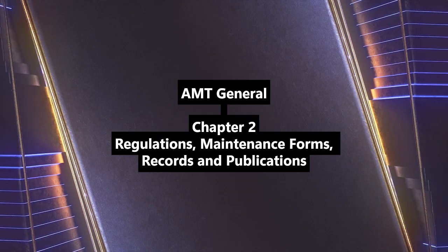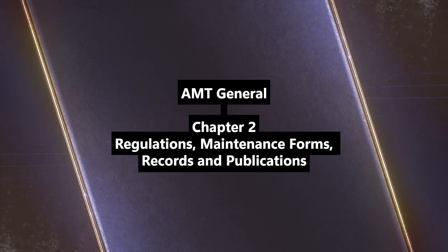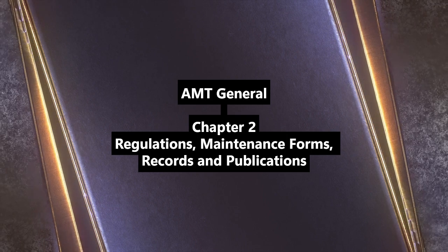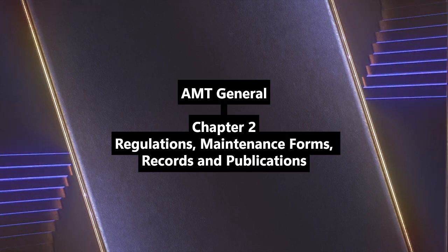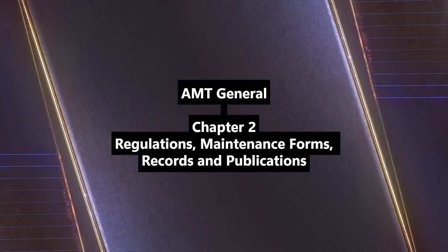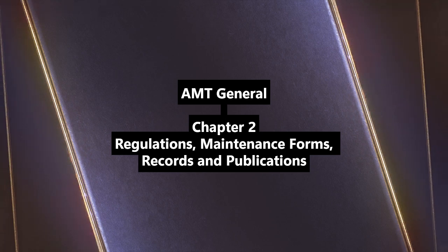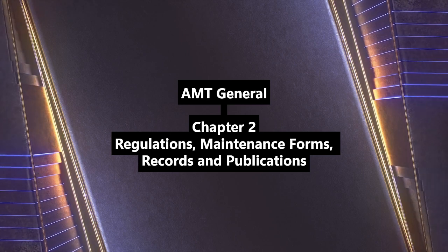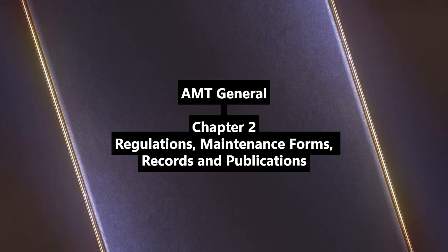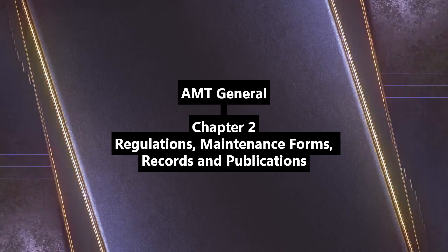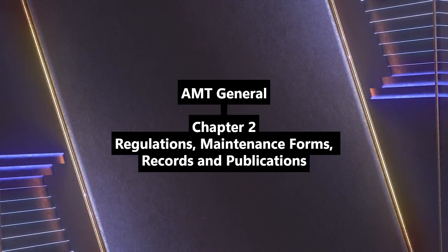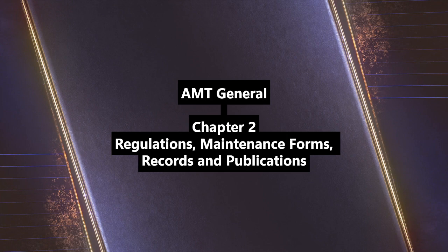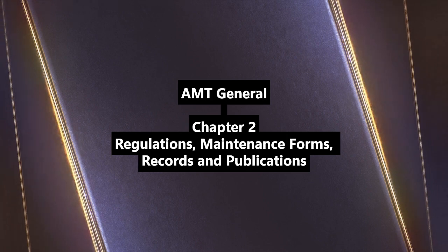But the approval for return to service must be done by someone specifically authorized under Part 65, using the repair station's certificate number. Okay. The sign-off is still tightly controlled. Exactly. They also need a detailed repair station manual covering organization, personnel, facilities, capabilities, training, record keeping, lots of stuff. How long do they keep records? Minimum of 2 years. And certificate validity differs for domestic versus foreign stations.